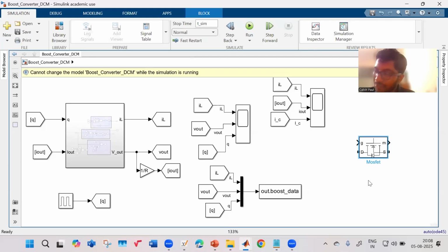Actually, I haven't worked that much in soft switching, so I don't have that much of an idea. But soft switching would require variable frequency operation. I had worked on critical conduction mode. Because it goes into critical conduction mode, I use constant on time control. The current will go to 0 and then I will turn on. So that is like a ZCS kind of way we are trying to mimic. That one usually ends up in variable frequency operation.